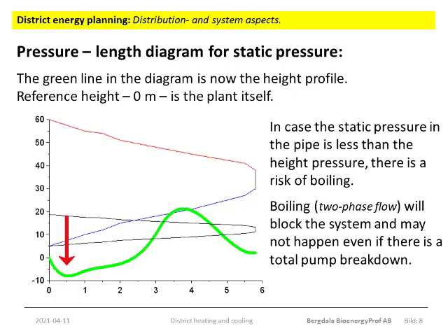At an 8-meter depression, the static pressure becomes 8 meters higher than it was at the reference level. And on the hill, 20 meters high, the actual pressure becomes 20 meters lower. So if the green curve is higher than the static pressure curve, there will be a negative static pressure in the pipe. And that may not happen.